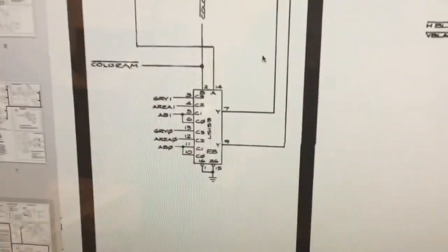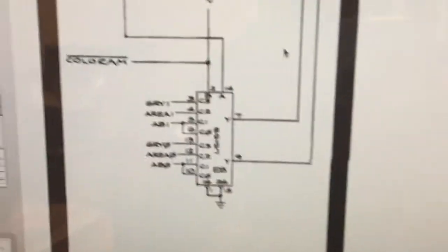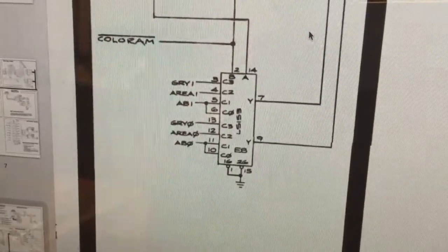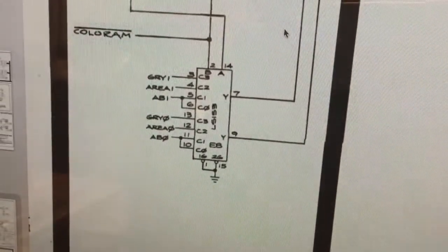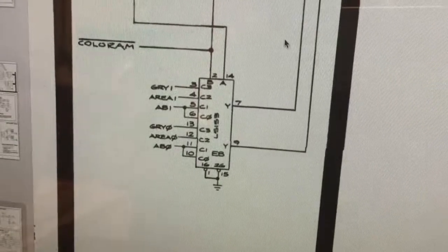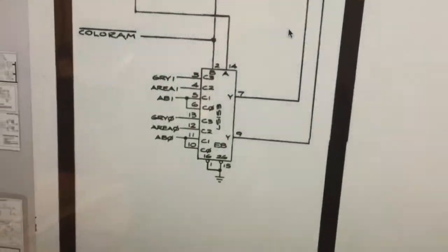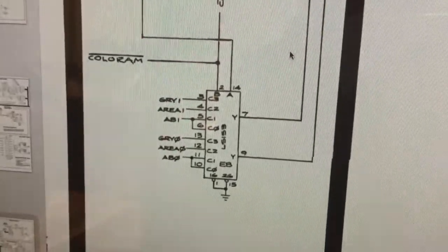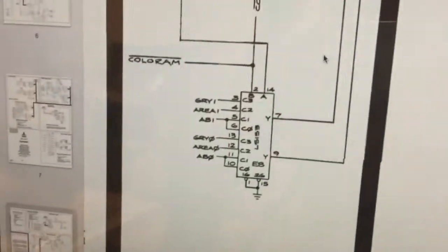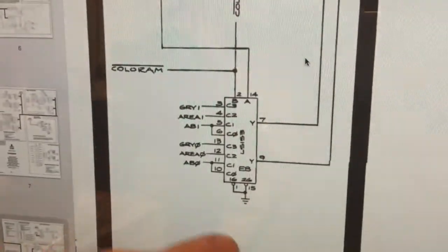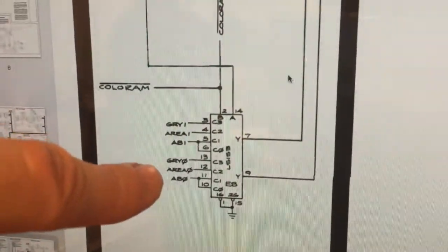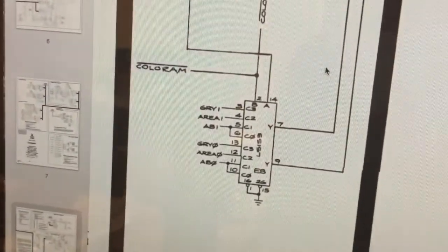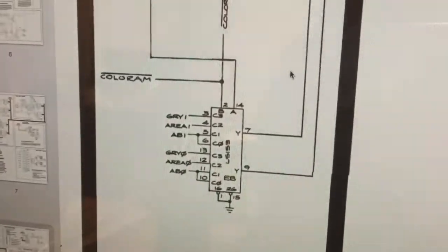for the Centipede PCB, we can see that there's a multiplexer down here that's getting some signals in, and I already looked into the motion object schematics, and I could clearly see that the output video signals from the motion objects are called GRY0 and GRY1, so those two are actually the output data that is generated from the motion object circuitry.